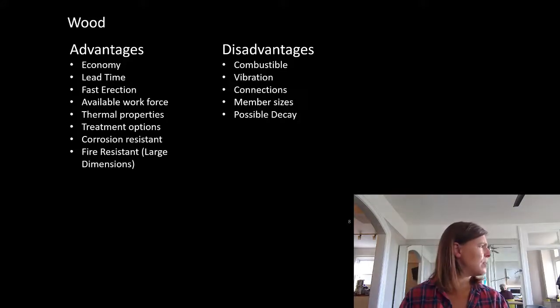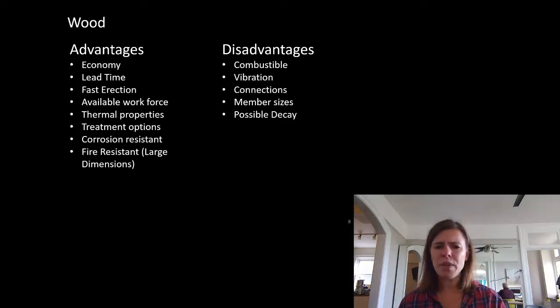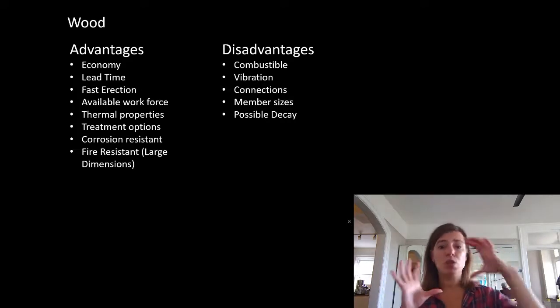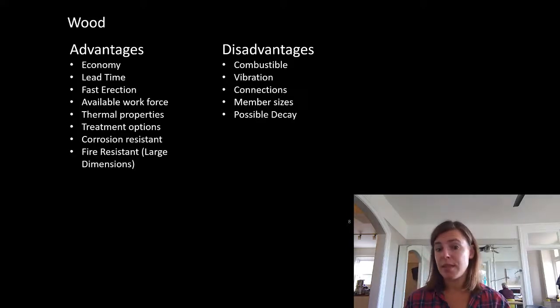Is it about an inch an hour? What is it? Something around that. Inch and a half, 41 millimeters. 41 millimeters, so an inch and a half an hour. As we burn that down, in regular construction, there is nothing left. But in mass timber, when we have big elements, or even if you're doing construction with some of the larger elements, maybe a 6x6, you can have structural properties left after a burn.